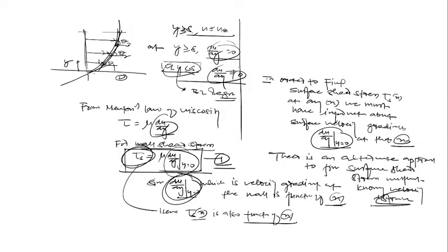देखो बेटा, if the velocity distribution is known to you, meaning u is a function of y is known to you, तो क्या करोगे आप? You should only differentiate with respect to y and put y equal to 0 and you can find the gradient, है ना? But this velocity profile is not constant, it is going to vary from one x to another x. So u is a function of x and y. So at the x at which you want to find the gradient, you should differentiate, put y equal to 0, and put it in this equation, and you can find the shear stress at that x. Is it clear? And shear stress is nothing but the momentum flux at that x. Is it clear?